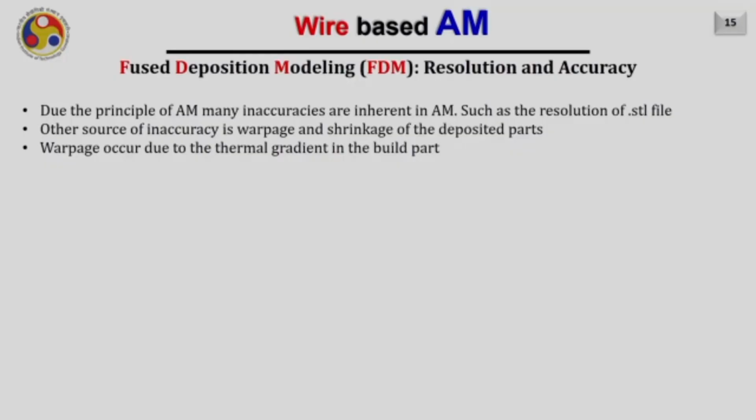That excess material is just to make sure that the steady state is achieved, and now the deposited bead is coming with a constant flow rate and your head is also moving with a constant speed. As the flow rate and the velocity of the head are constant, it is obvious that we will obtain the constant bead cross section as well.